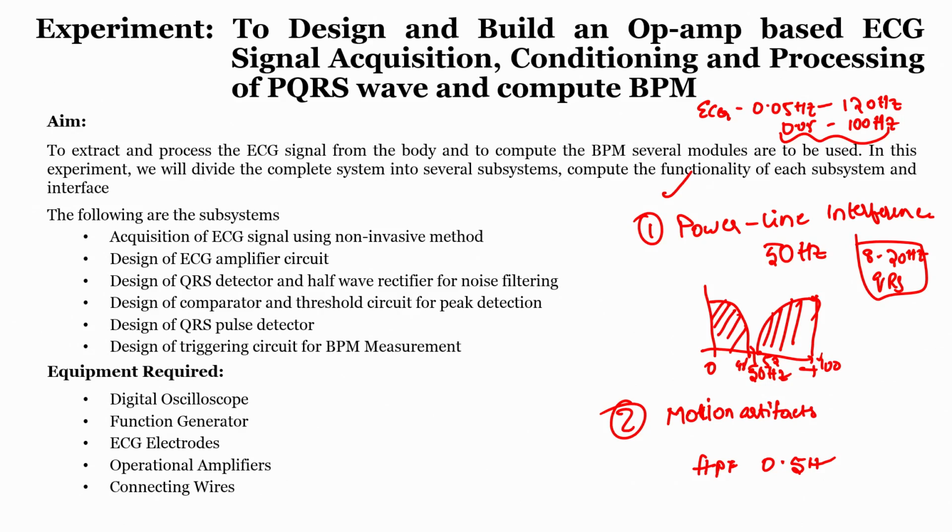Since it is not feasible to do in our laboratory, what we do is restrict ourselves to either first order or second order filters. Compared to first order, second order filters will have an even higher roll off factor, so it will always have a proper cutoff. We will also have a look into that, right.